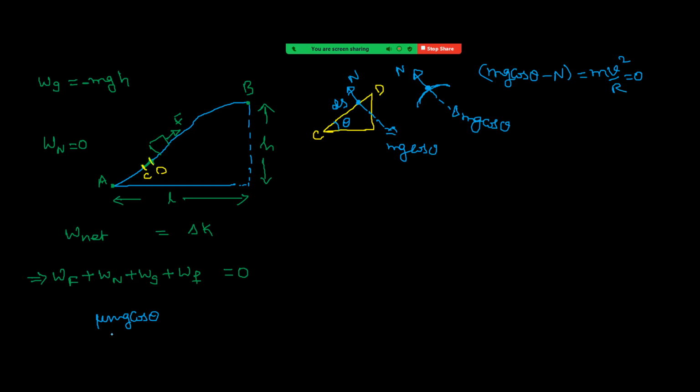Okay, right. So it is now mu into normal reaction, which is mg cos theta. This is now kinetic friction. Mu into displacement ds. Okay, and between this frictional force and displacement the angle is 180, because frictional force is down the plane, displacement up the plane. So I am taking a negative sign. Like this, we have to calculate work done for each and every small displacement. Okay, now integrate. So take the sum of all those things.